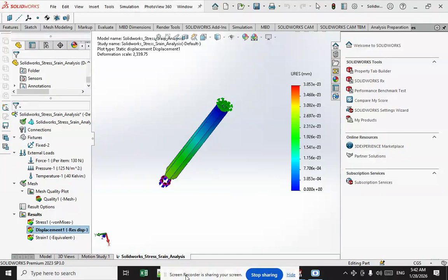Typically, the starting point for stress analysis is a geometrical description of the structure, the properties of the materials used for its parts, how the parts are joined, and the maximum or typical forces that are expected to be applied to the structure. The output data is typically a quantitative description of how the applied force is spread throughout the structure, resulting in stresses, strains, and the deflections of the entire structure and each component of that structure.